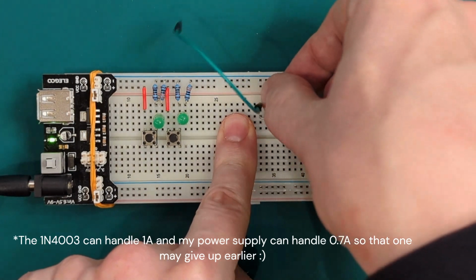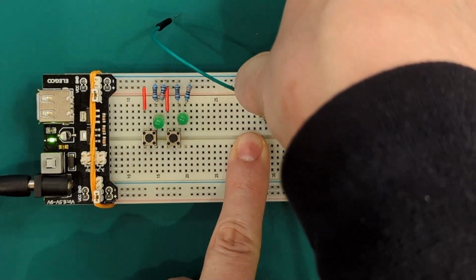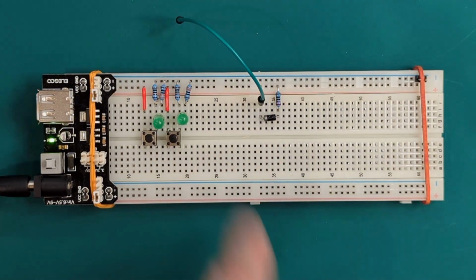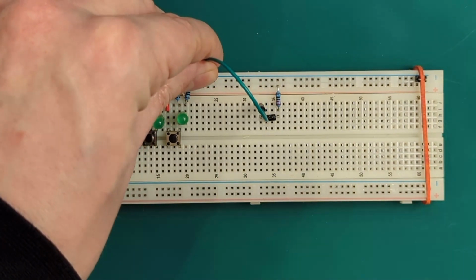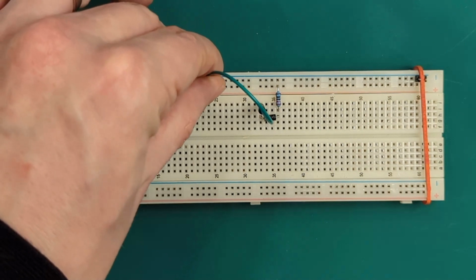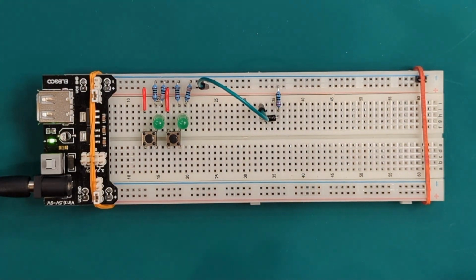So what I need to do is take this and add a small 220 ohm resistor here to protect the diode. So now current will flow only on a low input and it will stop flowing on a high input. So this kind of acts like a switch. Some of it is backwards in the sense of current flow and what opens and what closes it.